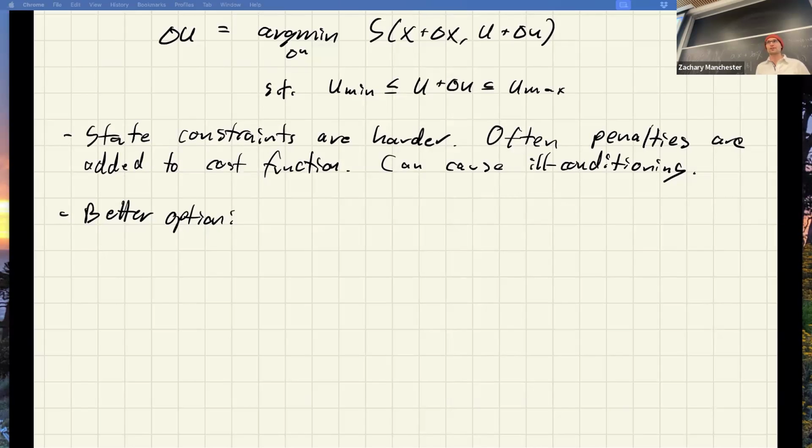So the cool thing about the augmented Lagrangian method is it takes your constraints and it basically transforms them into a quadratic and a linear term in the cost function, right? The quadratic term is that quadratic penalty, and the linear term is that Lagrange multiplier term. So it looks just like a quadratic plus linear cost thing, which is exactly what's in this DDP iLQR stuff, right?